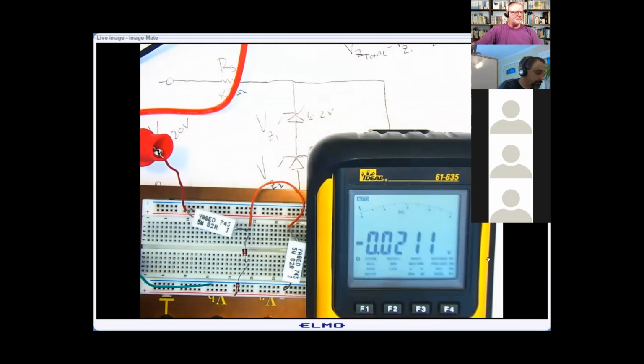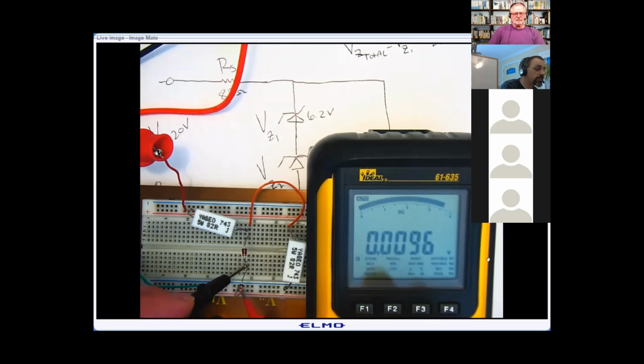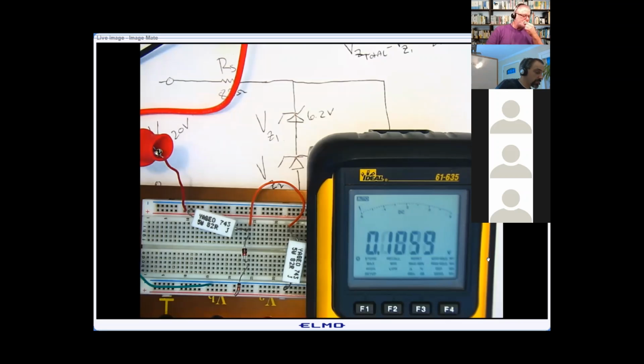Okay, here we go. What happens if I turn the voltage on? Remember, my source voltage is 20 volts. 9.8, pretty close. 9.8, 9.9, 10, 10.5. We're off by 0.5. I bet you anything one of these Zeners is probably not at 100%. There's that 3.62. Let's see what these Zeners are at. 6.2. So this Zener is off a little bit. Let me see if I kick this up a little bit. This 4.3 is not acting as a 4.3.